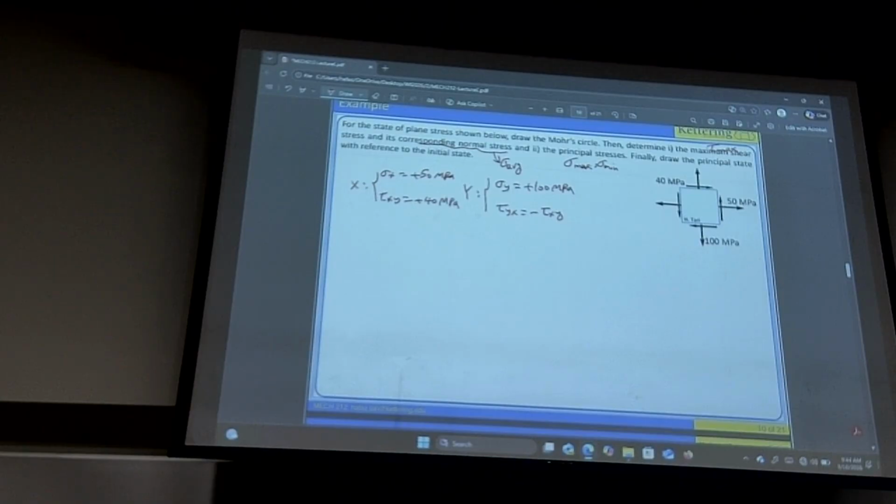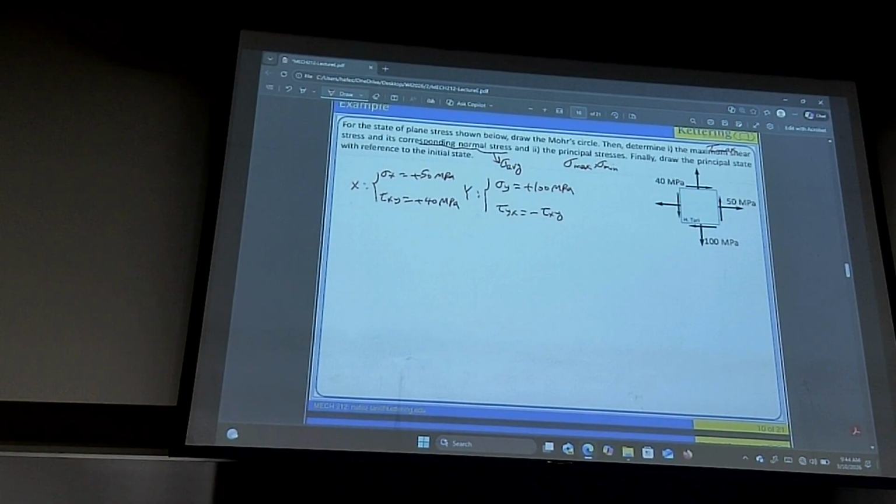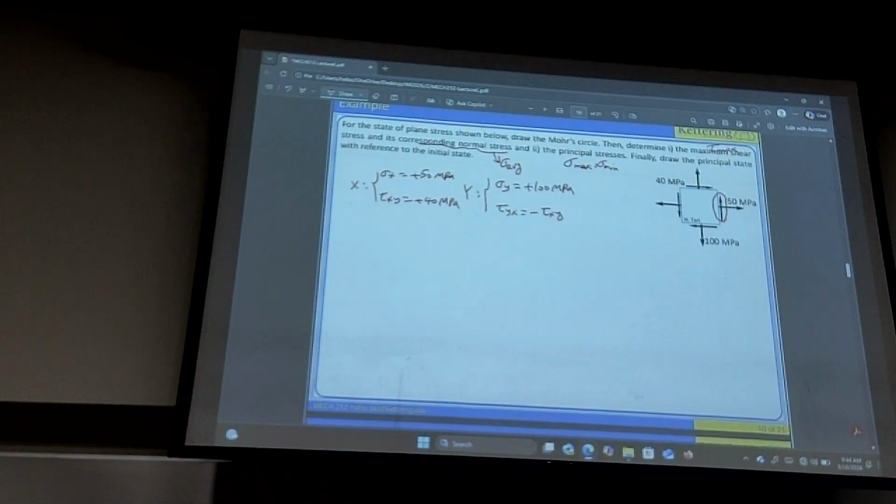Remind us how you determine the sign of this. The 100 megapascals is pushing down, which is a tension, positive in my mind. And then for tau, I'm gonna be honest, I just gotta guess on that. That's okay. This one, always look at this one. Upward, positive, downward, negative. Or the proper way is the one that you were about to mention: look at the center. Does this one create counterclockwise or clockwise? Counterclockwise, that's positive. Or should we look at this, upward, positive, downward, negative? Okay.